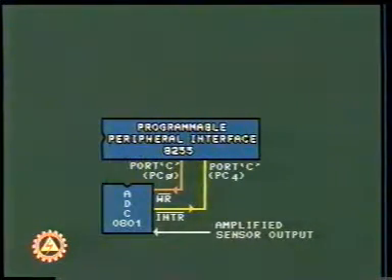The port A of 8255 is used in input mode and we connect it with data lines of ADC chip 0801. The processor reads the port A to acquire digital data generated by ADC 0801 corresponding to amplified sensor output.